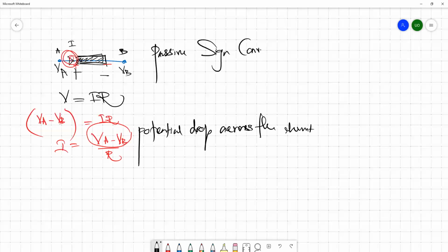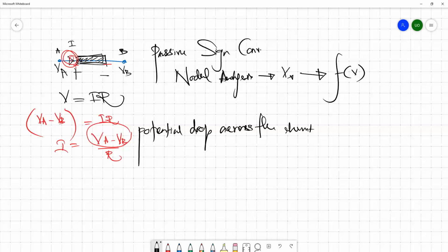Or, as we highlighted, if you have a network and you are planning to apply nodal analysis, it means we basically label all the nodes with voltages. So if you have 5 or 6 nodes, we just denote the voltages at each node as V1, V2, V3 and so on. And then you can apply nodal analysis. What you will end up with is a set of equations which are functions of the Vi's, the voltages at the different nodes. You can simply go through exercise 3 and get a clear idea about this.